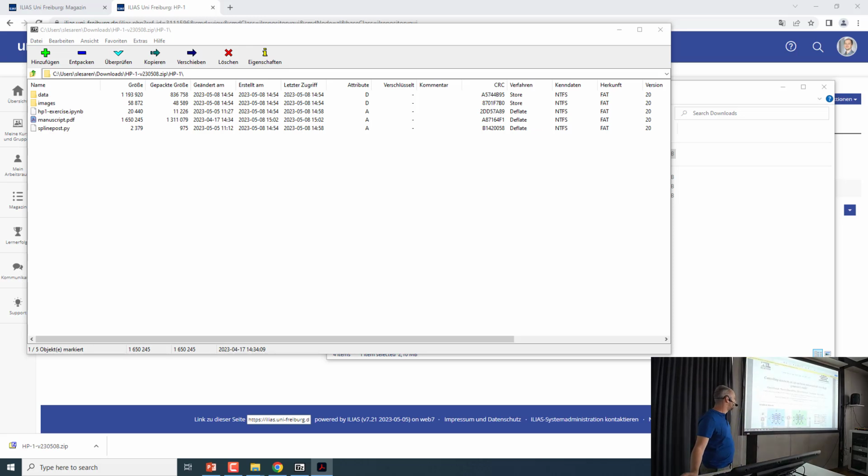And again, what you probably did before during home project 1, we just discussed this, which one? Generation, the right part. So you have some geometry and you get Poisson ratio. But of course, much more fun we have if we want to generate the geometry for the desired Poisson ratio. It's the so-called inverse problem, and it's a very common problem in any type of engineering. When you don't care about prediction of properties, you care about the generation of materials or structures with the properties that you want. So in this particular case, what we've done,